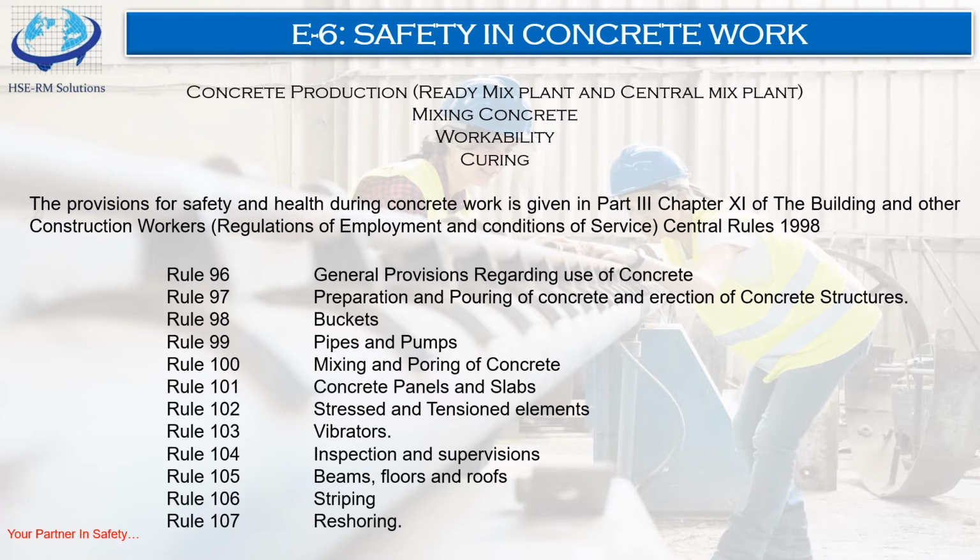It starts absorbing. Now the concrete plant consists of large storage hoppers for various reactive ingredients like cement storage, for bulk ingredients like aggregate and water, a mechanism for addition of various additives and amendments, machinery for accurately weighing and mixing some of those ingredients, and a facility to dispense the mixed concrete, often to a concrete mixer truck.